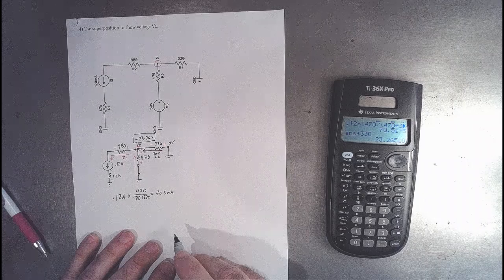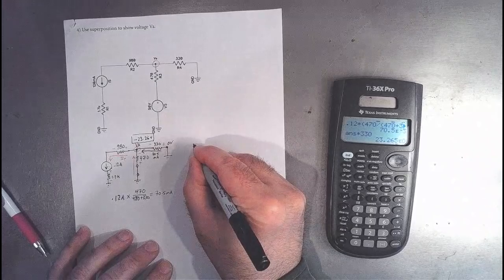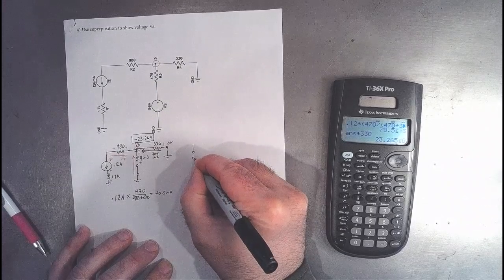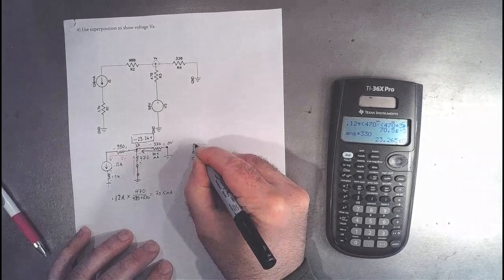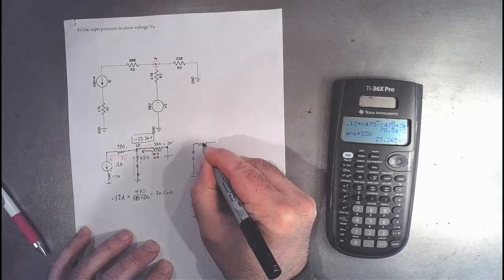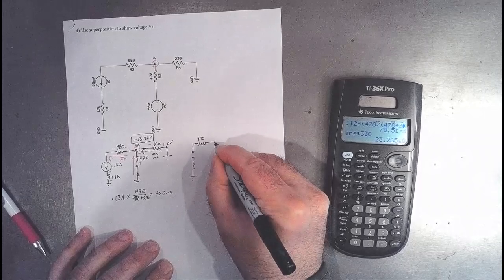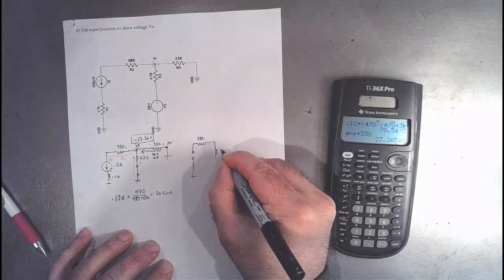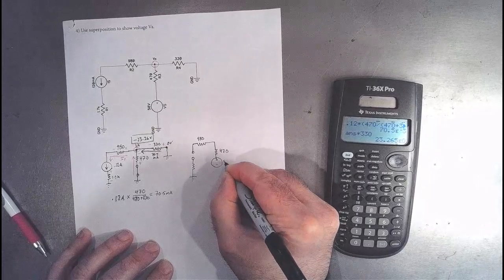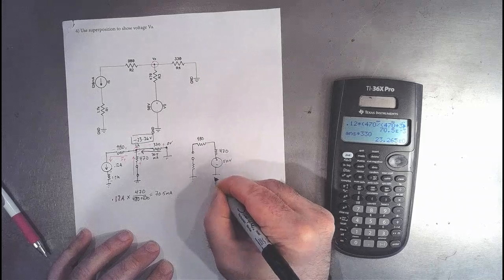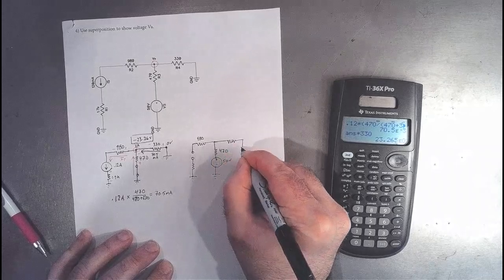Okay, well, now we need to know what the voltage source is contributing to this. So I need to remove the current source. How do I do that? I open it. All right, well, that cuts off this whole leg of the circuit right there. And there's no current flowing through the 980. Here's the 470. Here's our 50 volt source. Here's the 330.